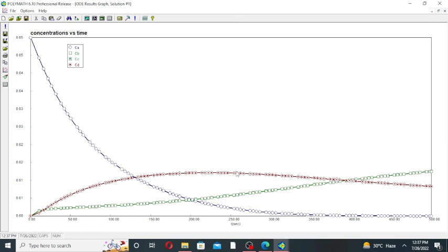But if you see from this point, after 400 seconds, if we further add component B to the semi-batch reactor, then the concentration of components C and D will decrease, because the reaction is completed and we are entering further component B to the reactor, so component B will be diluting our product.